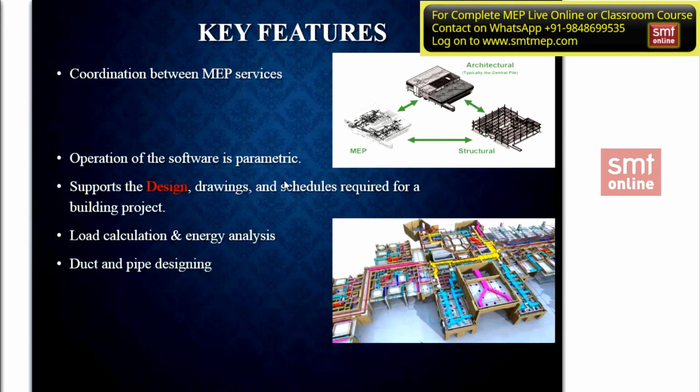Next, duct and pipe designing. We don't require a separate duct sizer or pipe sizer in Revit, because Revit offers tools for duct and pipe sizing as per the required methods. So you can expect different methods for duct sizing, like the equal friction method or static regain method or velocity method. Even for piping you can go for the velocity method or the combined velocity plus friction, etc. So no additional duct sizer or pipe sizer is required. You can use the inbuilt option within the software.